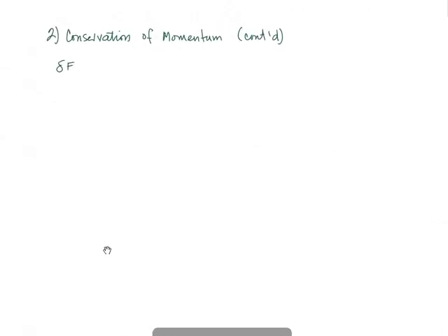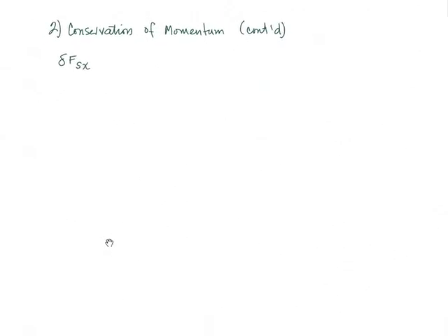Let's write it, df s for surface and x because it's the x direction, and that's going to be equal to, well, we sum all of these components and you see that because some of them are pointing towards the right and some of them are pointing towards the left, then the signs will turn out to cancel out all the terms sigma xx, tau yz, and tau zx, and we're going to be left only with the variation terms, which are ddx of sigma xx.